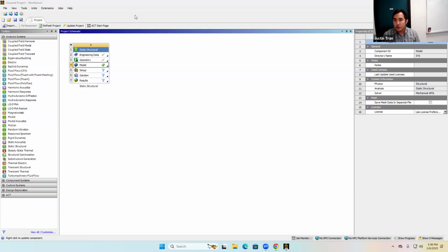So you can use a parasolid file format. That's the one we're using today, so that's .x_t. That's my personal favorite one, just because it's a parametric file format, so it retains basically all the information for you. Another common one that's used is IGS, so that's either .igs or .iges.